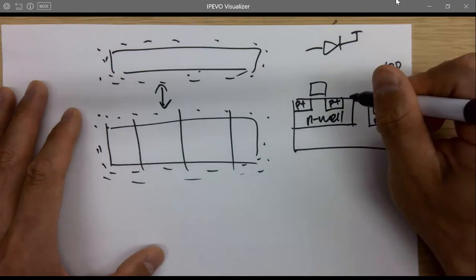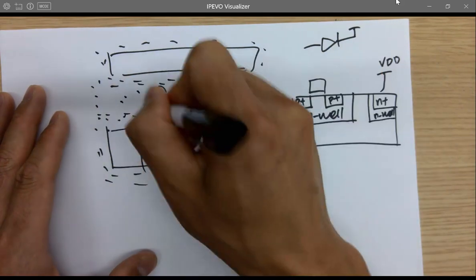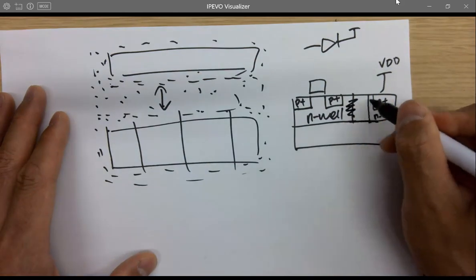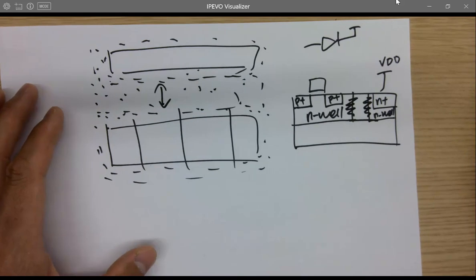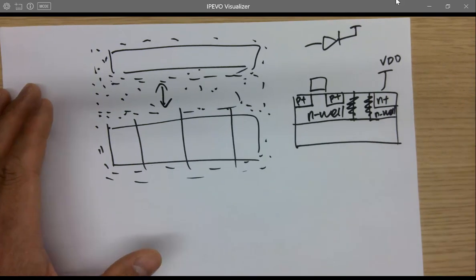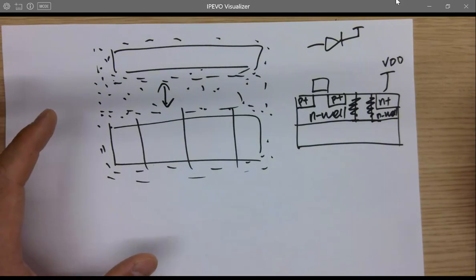Okay, so I placed a pure dot layer in here, so the foundry knows it's one piece of N-well, right? It's one piece of N-well. So if you are laying out that same process, but with an N-type background, technically you wouldn't have to connect them because the background is also N-type by default. Mm-hmm. But yeah, that's right. It's confusing the foundry. Like, you need a different wafer? Yeah. Okay, that makes sense.